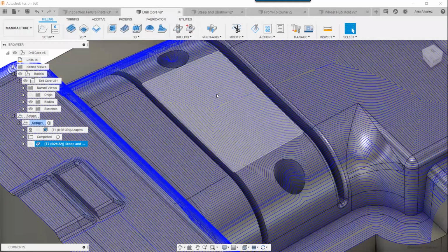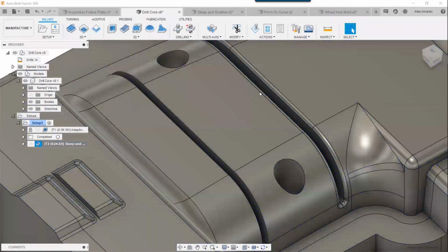So with smooth offsets, the software modifies the toolpath slightly. It doesn't make a dramatic change, but it rounds this off so you have a more continuous and smoother transition. That's just another option that you can enable there.